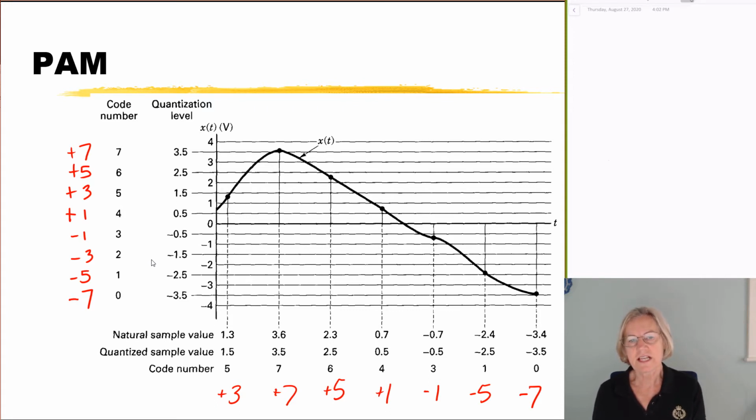For instance, instead of assigning 3 bits, I could put in a certain discrete level. And for convention, we usually use these odd integers as a representation of the levels we use. So you can see that there's plus and minus 1, which are separated by 2. If I go to another 2, it's plus 3, plus 5, plus 7. So these are just arbitrary reference numbers, which make it easy to count. But in this case, you can see that we have 4 discrete levels, which are going to be used to send information from the quantization. So these are both valid ways of turning analog data, quantizing it into digital data.